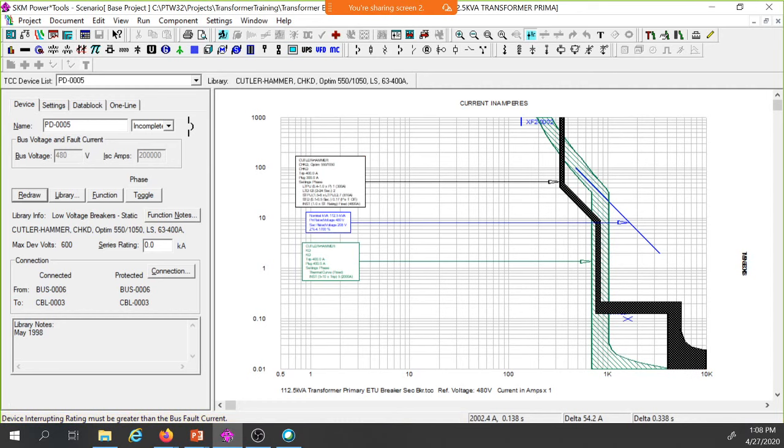You should be plotting that curve and understand that the inrush current needs to be below this. It usually lasts around 0.1 seconds. You could be a little bit longer, but it's probably going to be lower. Every transformer is going to be different. That's the other challenge. The rule of thumb that we use is the inrush current for 0.1 seconds. Could it vary from that? Yes. Could it vary every time you energize it? Probably, depending upon the closing angles and everything else that you have with your system. That's probably a worst case scenario, 0.1 seconds.